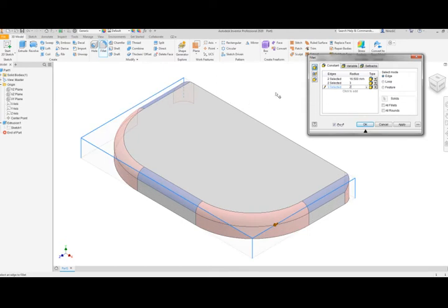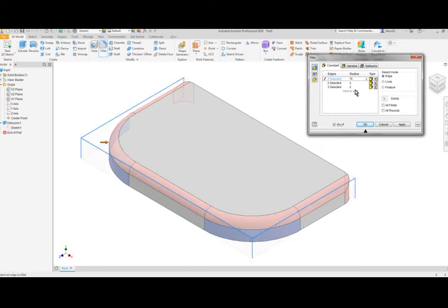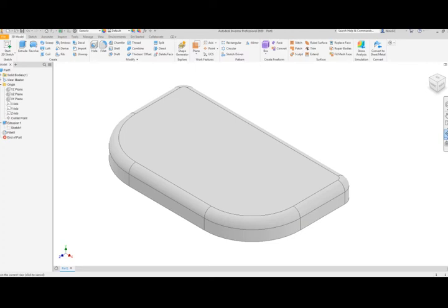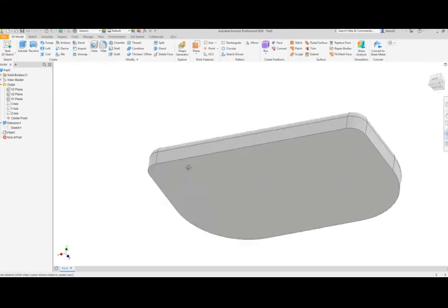So by doing this, we actually have a group of 3 different fillets, starting from the corner edges. I'll make an adjustment, I'll make that say 14. We have the opposite end, which is 3 millimeters, and then we have the top end, the top portion, which is also 2 millimeters. I'm going to also add this edge to finish it off and cap it, and then click OK, and now I have my fillets.